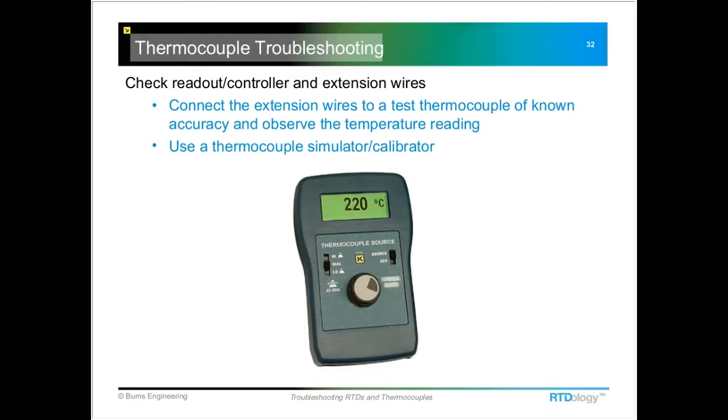One of the questions from Matt is he has a type K thermocouple, and the temperature drifts upwards and sits about 5 to 8 degrees F too high for about 15 minutes after power up, and that's at room temperature in air, and it's apparently just sitting on his desk. So he's wondering what might be the situation. Oh, that's very curious.